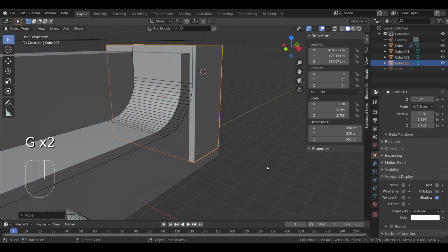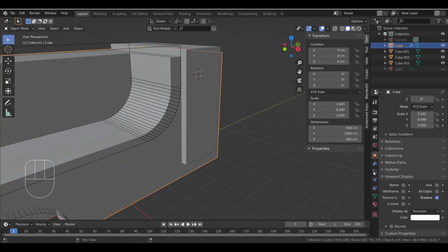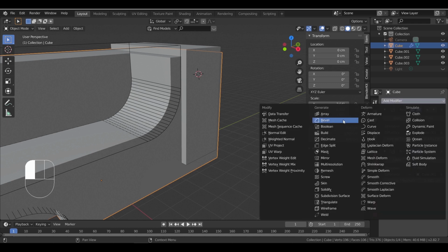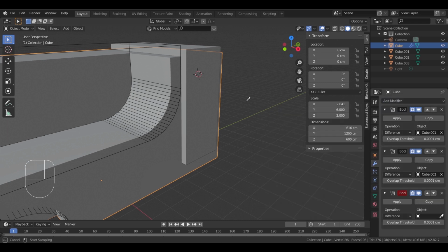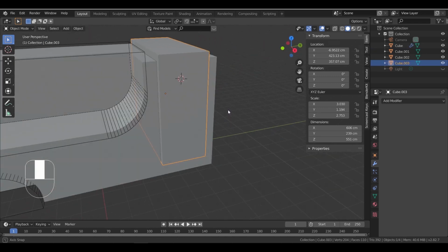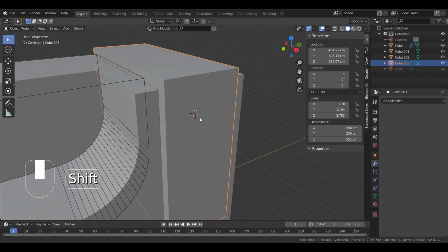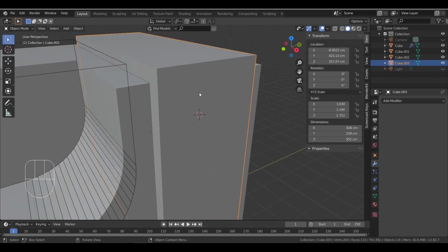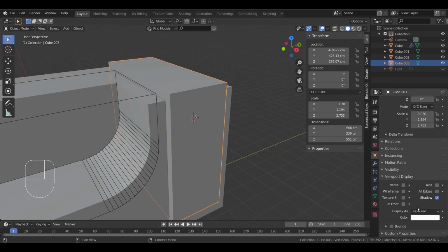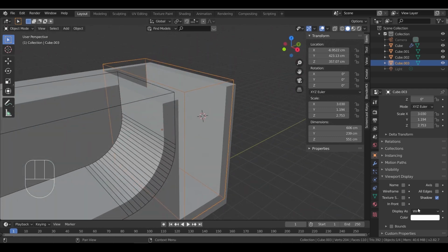Once we finish with that, we need a new Boolean modifier in the main cube to cut the area of the intersecting mesh, and as before, we take the pin icon in the new Boolean and select the mesh needed. After that, we change the preview to wire to make sure the Boolean works fine. But this time, we change it back to texture.